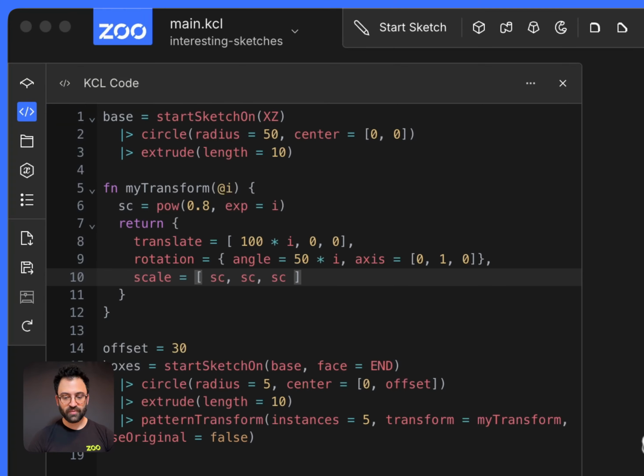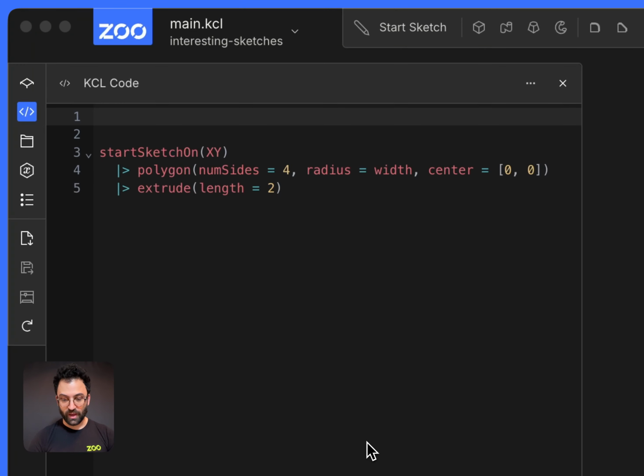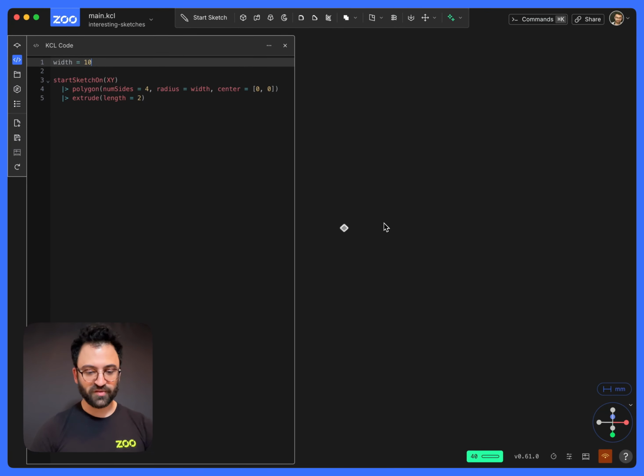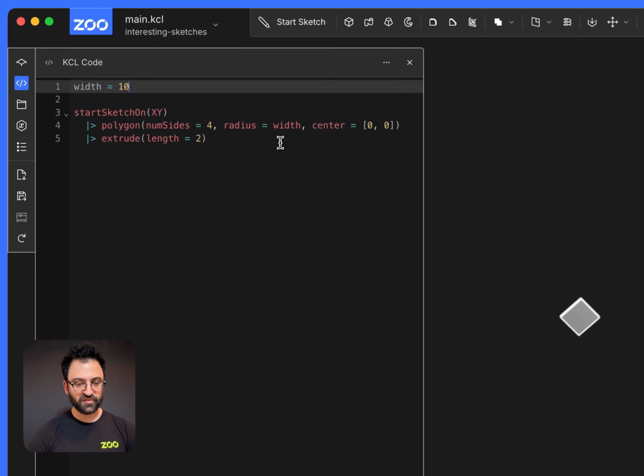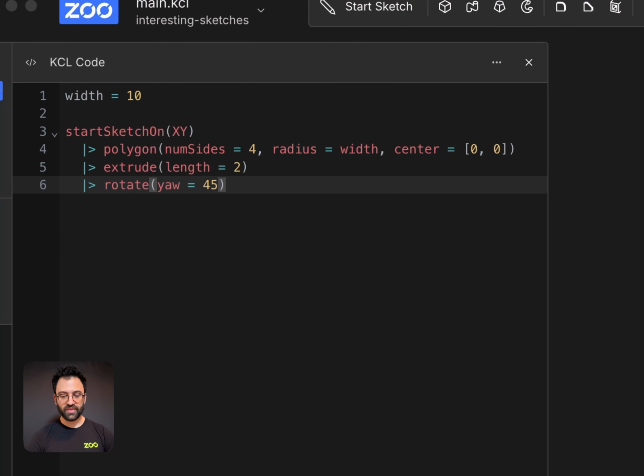We're going to define a couple of basic things first. Firstly, let's make one square for now. Let's define width. Let's say our width is going to be, I don't know, 10. Width equals 10. Here, we've made a square. And let me align that so it's head-on with the camera. Let me put in a rotate tool. There we go. Now I want to replicate these in a kind of chessboard style.